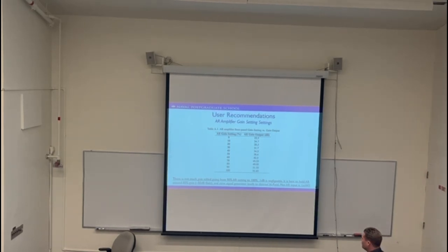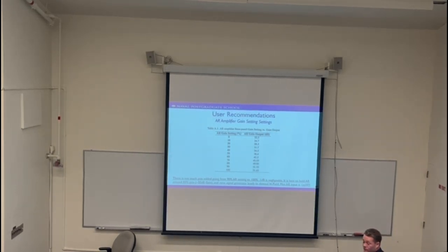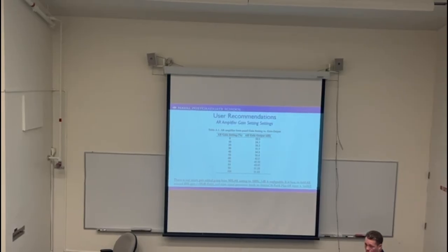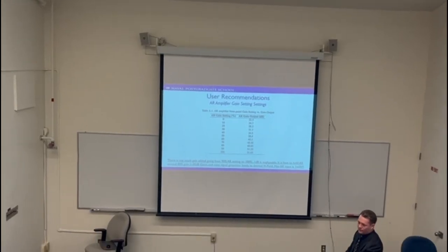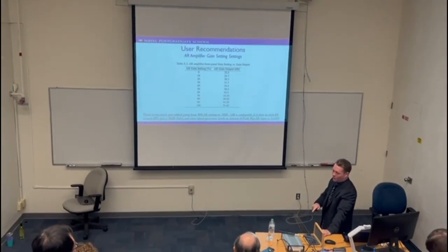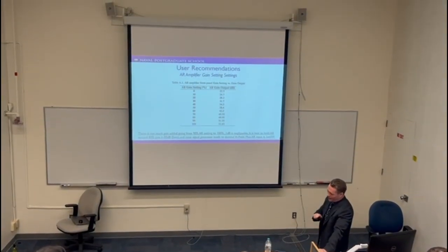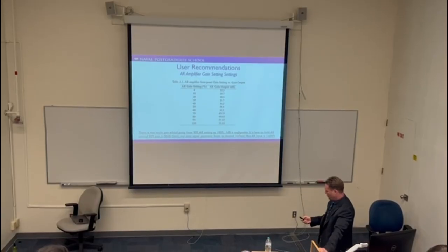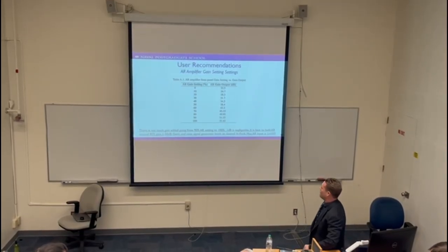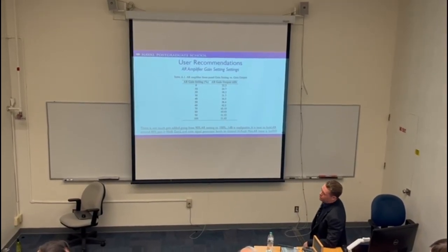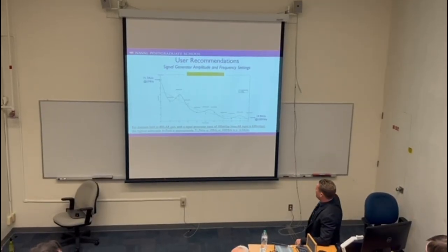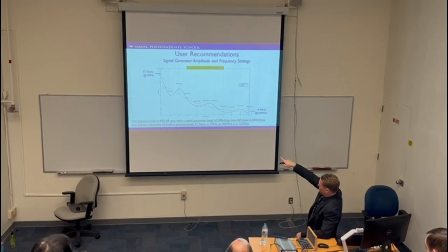I also need to remember that I can only put in 630 millivolts peak to peak, which is 1 milliwatt, into the input of my AR, or I'll blow it out. I can't say that. Again, they're tanks, right? So they know people are going to put a lot more than that into it, but they don't recommend exceeding that. So you knew that 630 millivolts peak to peak was our max signal generator input we could put into the AR.